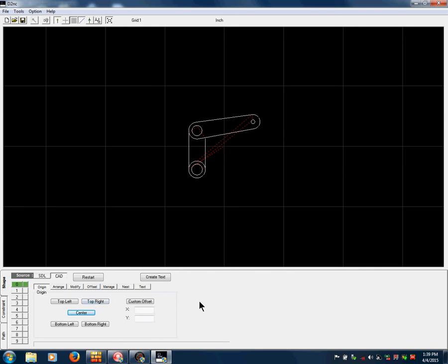I've decided that I'm not going to use that 11/16 cutter. I'm going to go ahead and do this with the high speed head, and I'm going to do it with 1/4 inch cutters, and I'll cut around this profile and this profile, and that'll remove this center section I was worried about before. I don't want to change from using the regular mill spindle to the high speed spindle. I'm just going to leave it all in high-speed spindle and do it with a 1/4 inch. So a little change up. I'm not really sure what I'm doing, so follow along and we'll see how it goes.